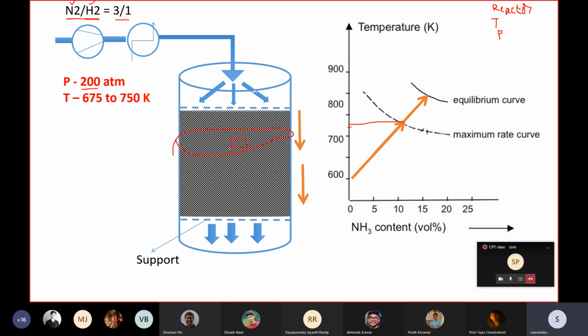Yes, your guess is correct that we need to circulate cold water. But with a packed bed reactor, especially a high pressure reactor, the practical difficulty is that when the thickness of the reaction vessel is higher, if you circulate it, only the outer edge may get cooled down, but the inner part will not.